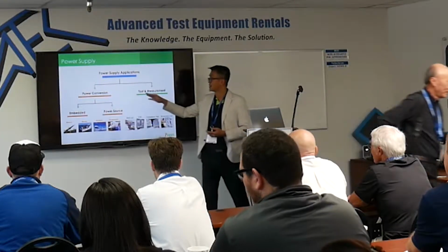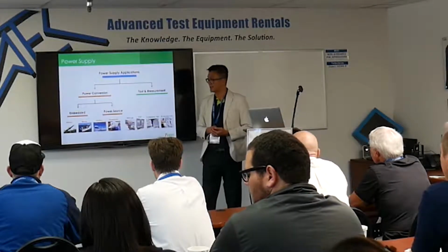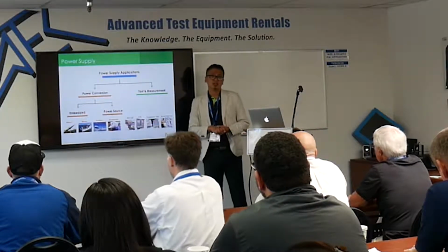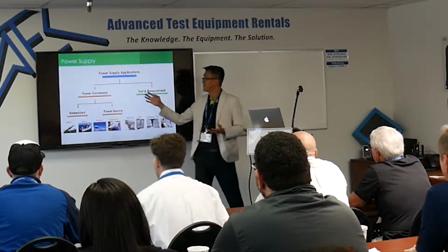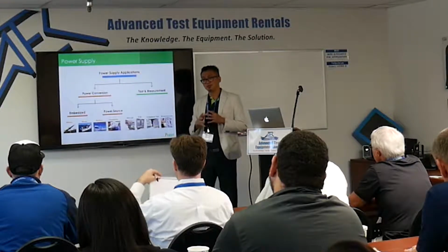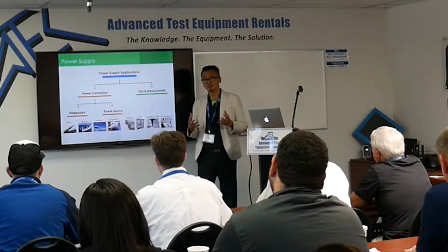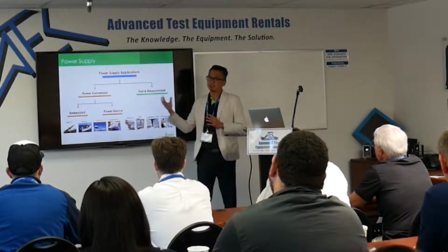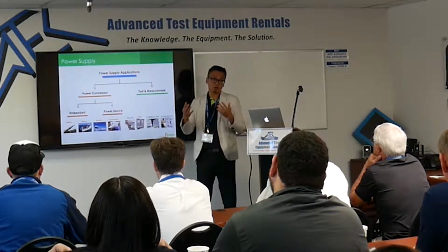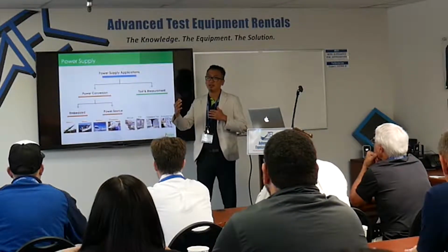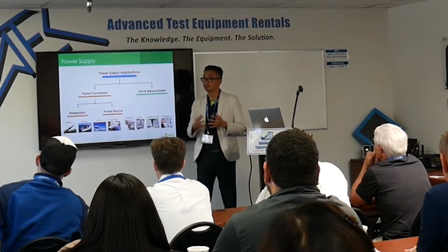The other use of power supplies is sometimes called power conversion. What's the difference between testing and power conversion? A testing power supply usually needs more features, like adjustable voltage and adjustable frequency, because you can do upper bound, lower bound, and boundary testing.